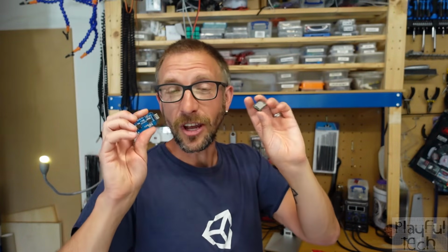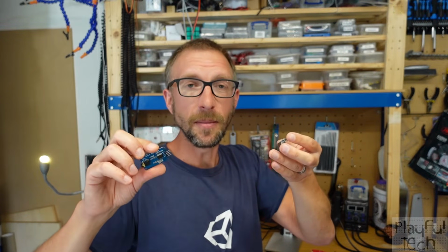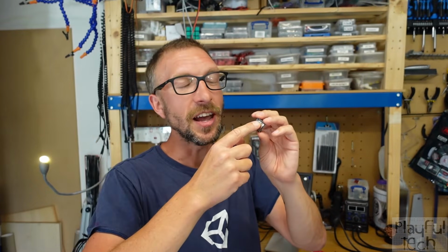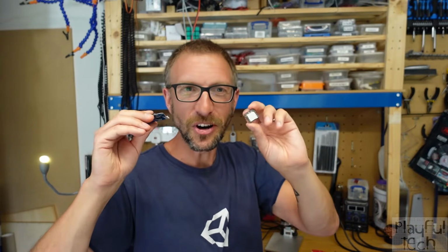They don't all produce the same audio quality. Some produce noticeably more static or hum, or they introduce a longer delay before playback, or you can hear high frequency clicks when the SD card is accessed. And there are also some more advanced features like navigating to a particular folder or playing a specific track by its file name that are simply not implemented on certain chips. And there's no way of knowing when you buy one of these boards which chip it will use.